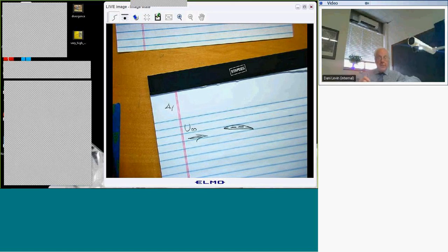It's also not true if I put this at a given angle of attack and then oscillate about that angle of attack. In supersonic and subsonic flow, the lift or other aerodynamic forces through the oscillation itself don't really depend on that small angle of attack. But in transonic flow, it does.